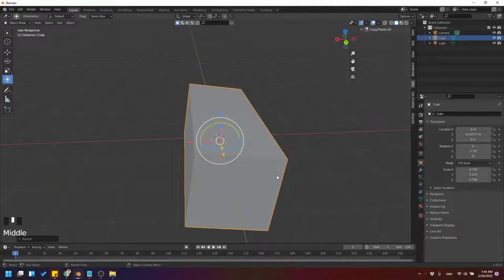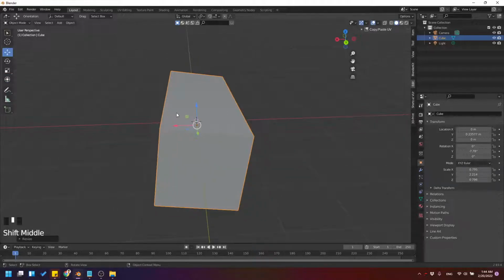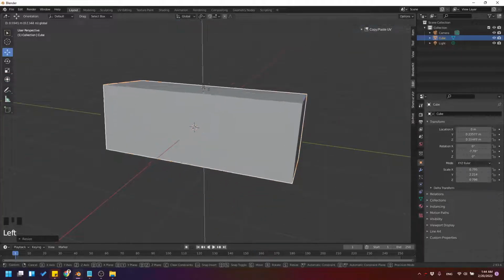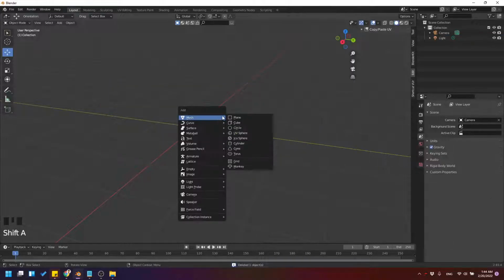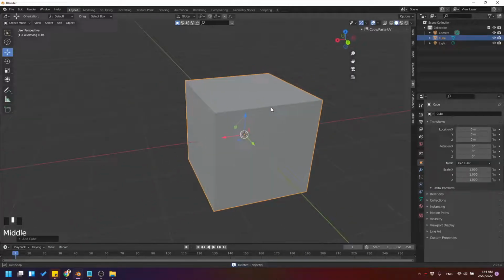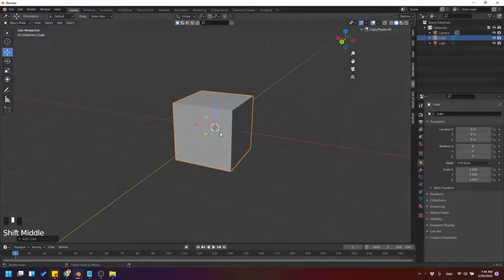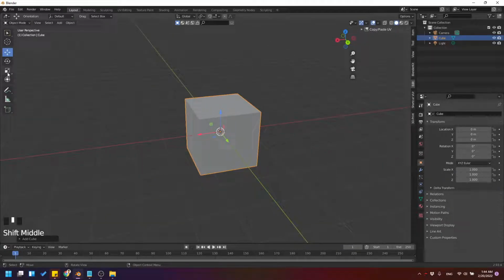For now I am going to click on move, and now it is selected like a gizmo, and we can press X and delete, and Shift A again and create a cube. I have created another cube for now. So here we have covered up to scale and transform.